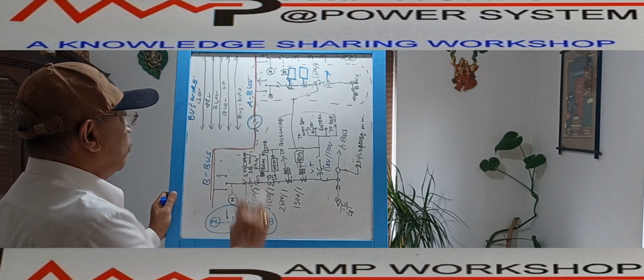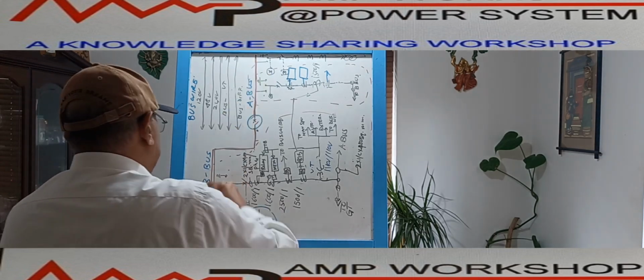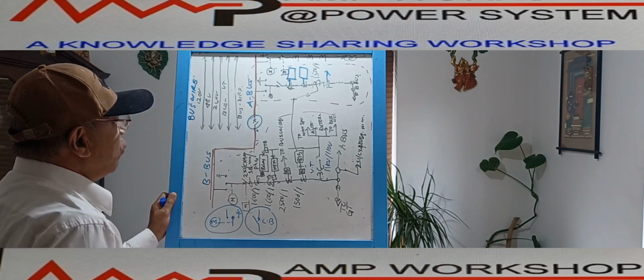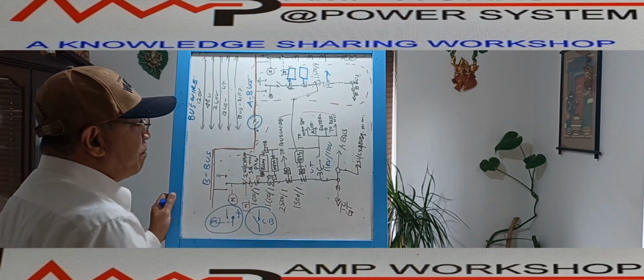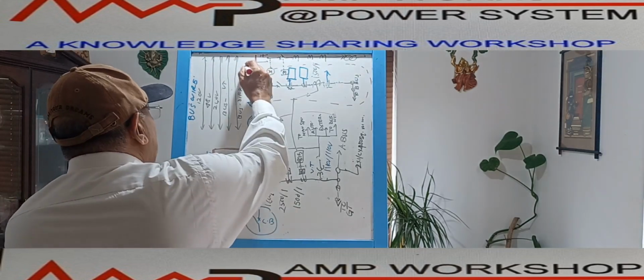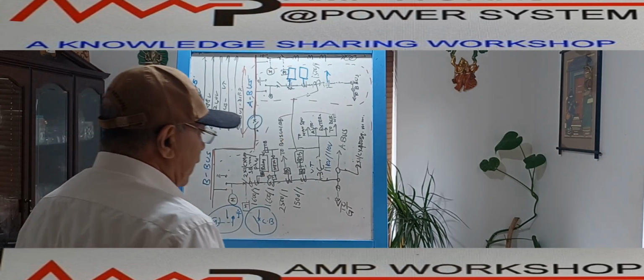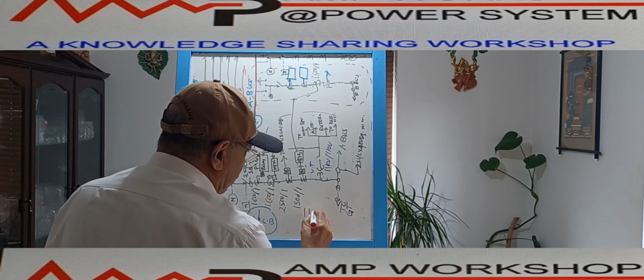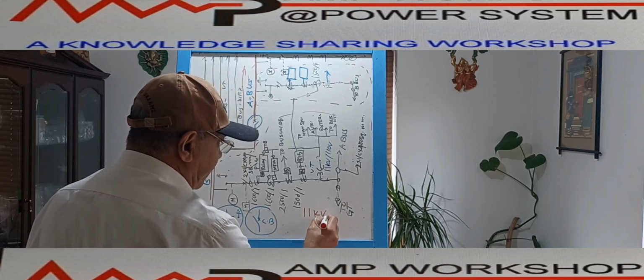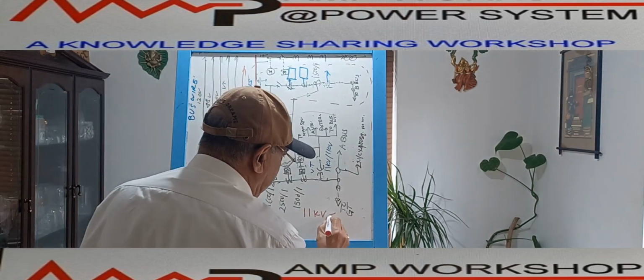Now when we are drawing the switchgear, first, over the bus bar, over here, we have to write down the brief specification of this switchgear. This switchgear is an 11 kV switchgear. So in this location, over the single line, we can write down that it is an 11 kV switchgear. That is first of all 11 kV. What is the current rating of this switchgear? Suppose this switchgear has a 4000 ampere rating.